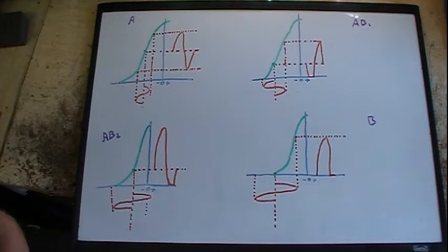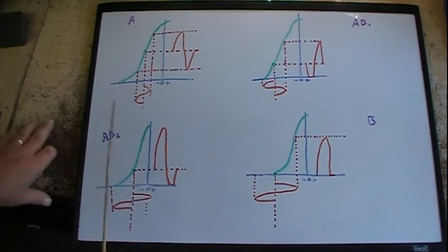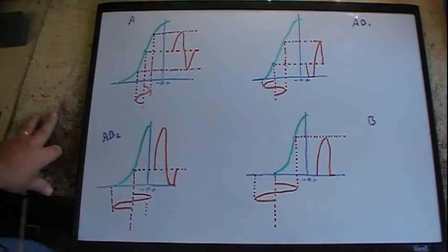That voltage divider is not just strictly for the output tubes or audio. It is applying bias for the diode detectors. It's biasing those as well as the front end on that particular radio especially. So it's used for different biasing of different tubes throughout the radio. So it's already there. This way you can make use of it.